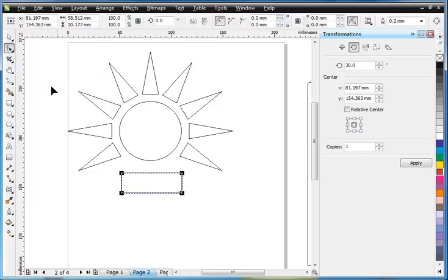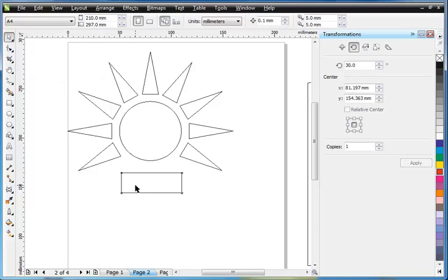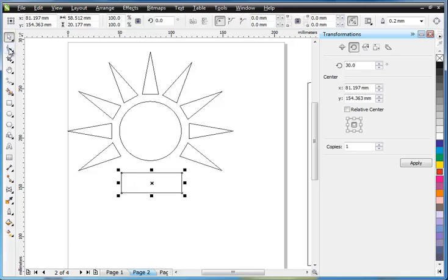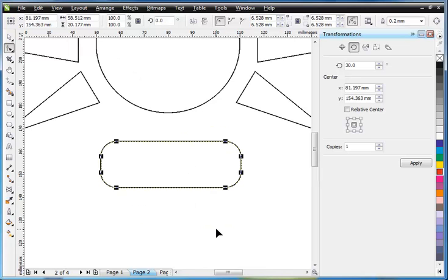Let's go back and analyse this situation. Before we selected the Shape tools, our rectangle was already selected. When we switched to Shape tool, 4 nodes appeared in each corner of the rectangle. Click on one of these nodes, hold the mouse button and move it. All nodes will move, creating nice round corners.